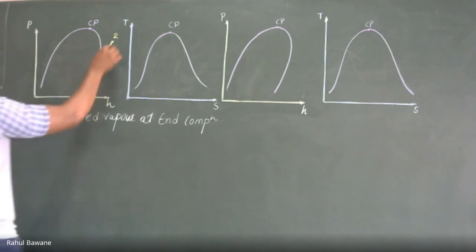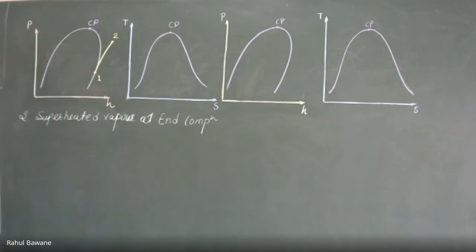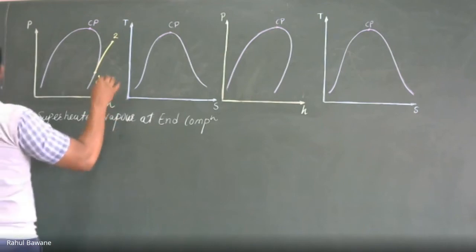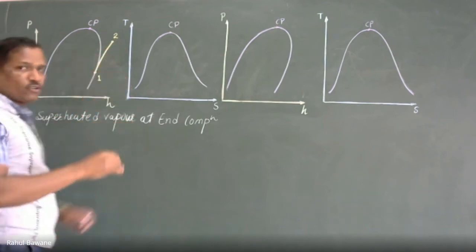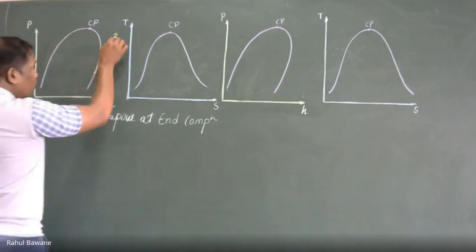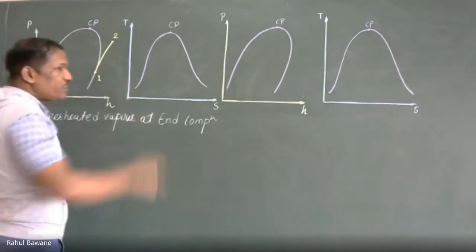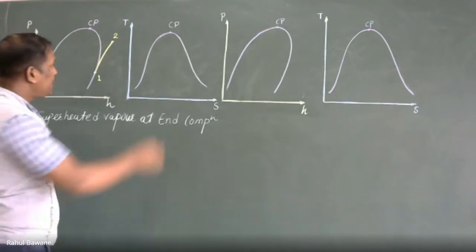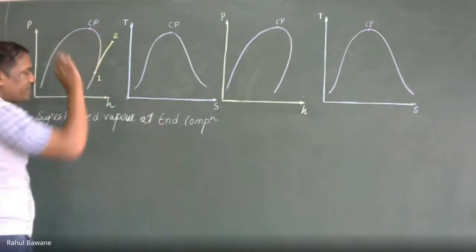So if your steam is at superheated condition, when I supply it to a condenser, it is not going to convert directly into liquid form. Why? We have to reduce this degree of superheat and bring our vapors to dry saturated condition.